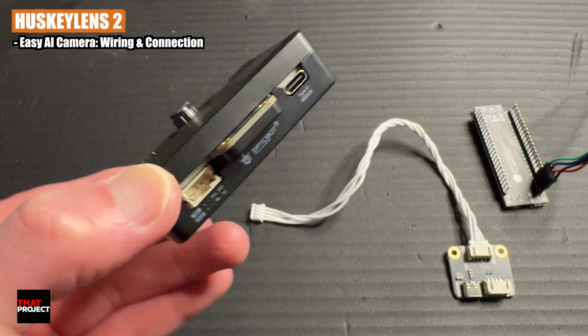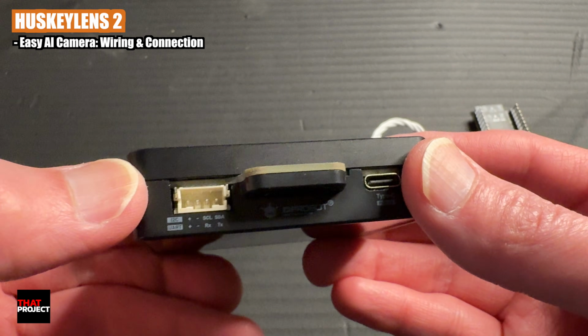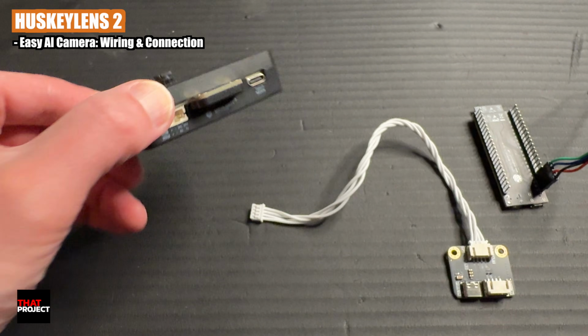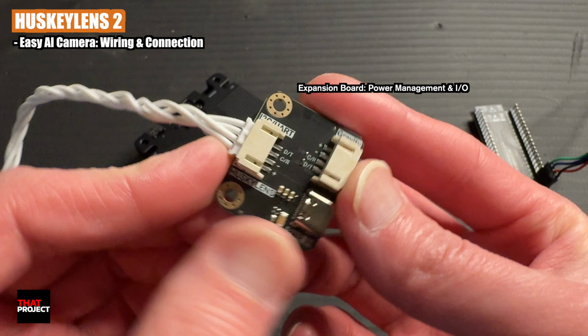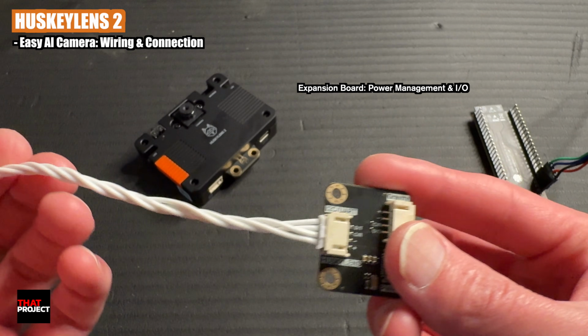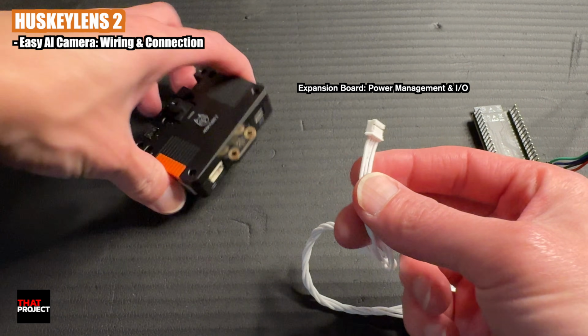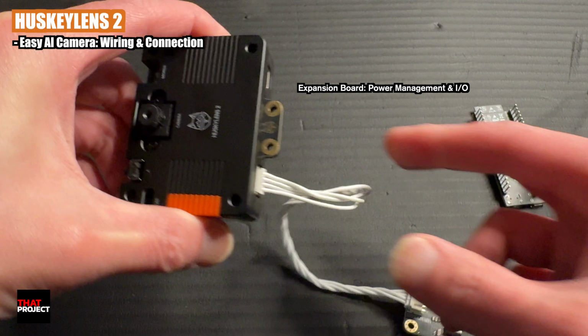Now for the connections, the HuskyLens2 is flexible. It supports both I2C and UART. Since setting up UART on ESP32 is basically a walk in the park, that's the route I'm taking. In the box, they include this little breakout board. This helps us manage the external connections and the power supply without making a mess of wires.